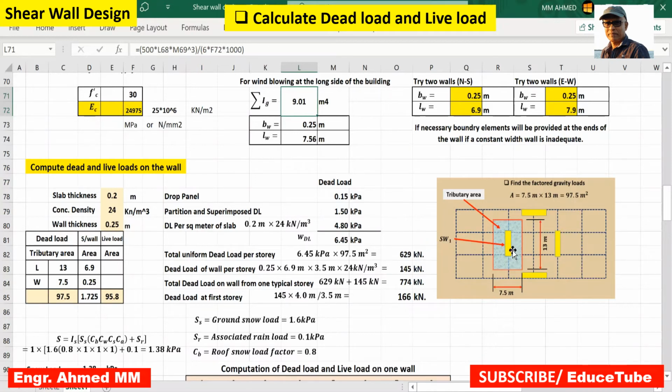Now question is, in this tributary area there is a load from this wall also. So what is that load? 0.25, 6.9, 3.5 is the height of the wall, 24 density of concrete, so we get 145. Now adding these two, we get this total load on wall from one typical story 774.